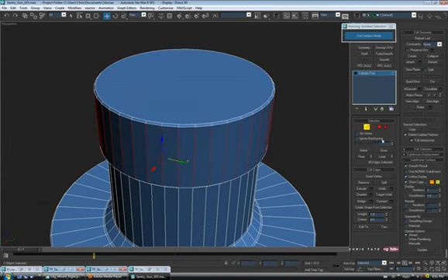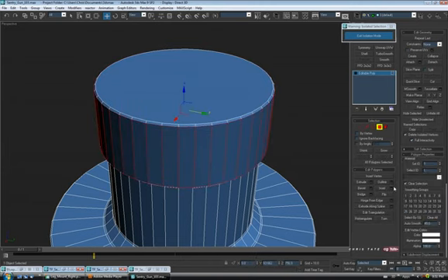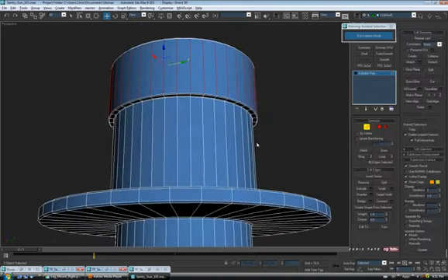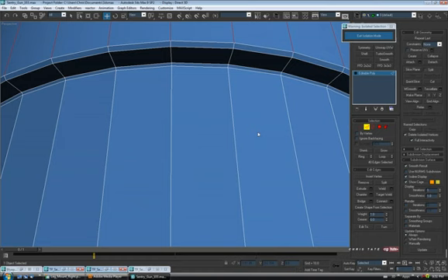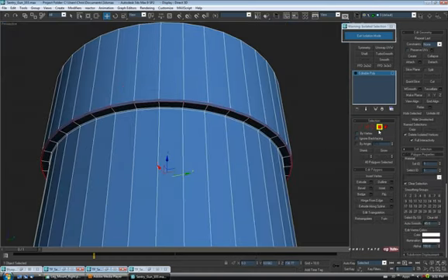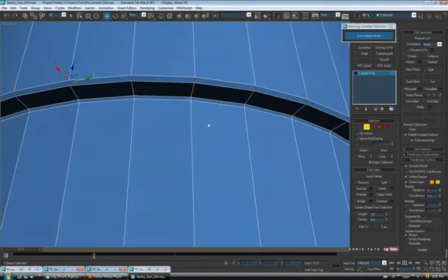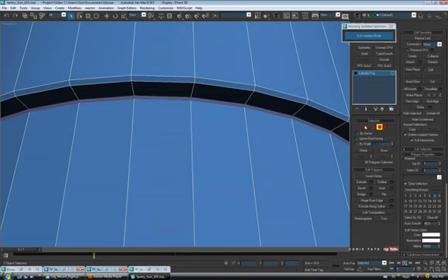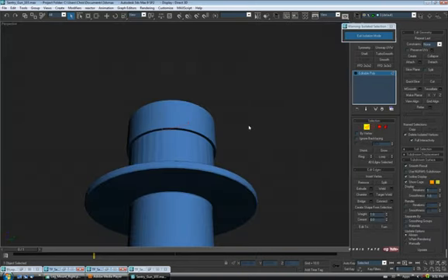It doesn't really matter which one you use. Alright, so we'll do the same thing here, ring, and then control click polygon, and we'll give it a different number. And I'm just going to repeat this on pretty much every chamfer, all the way down. So ring, control click polygon. Underneath we don't need to do it, but I'm going to do it right here on this chamfer. If I can select it. There we go. And I'll try to do this fairly quick because I know it's a little tedious watching it.